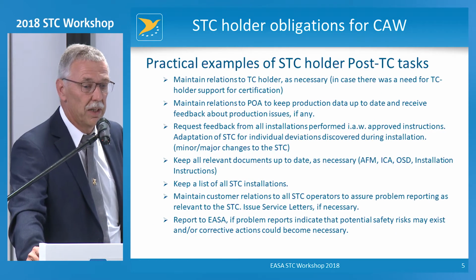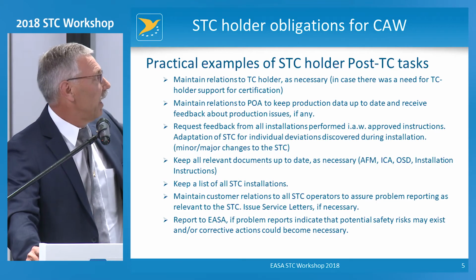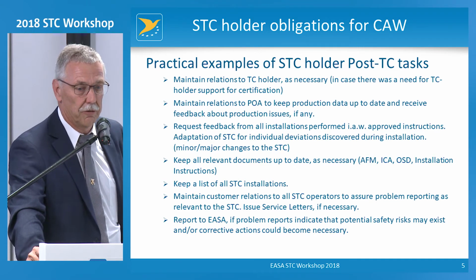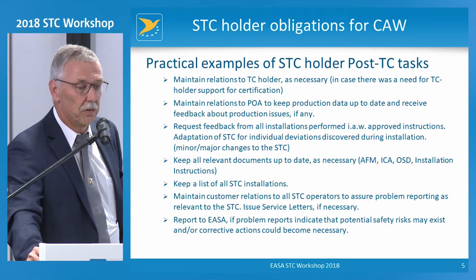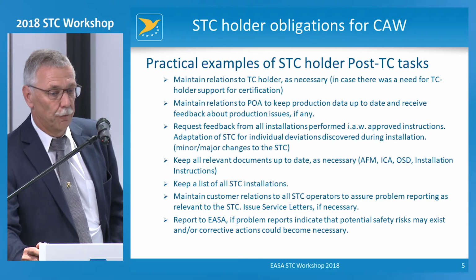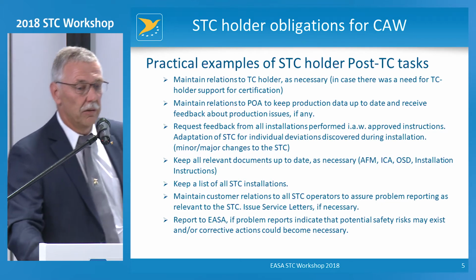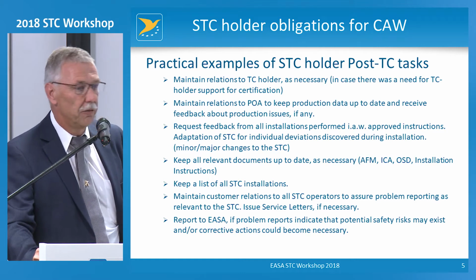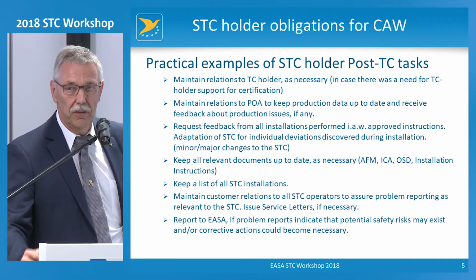Practical examples. The header of the slide says obligations for continued airworthiness. I would rather say this is best practices for how to be prepared for the unexpected. You have to maintain relations to the TC holder, if you had some credit when you were designing your STC.